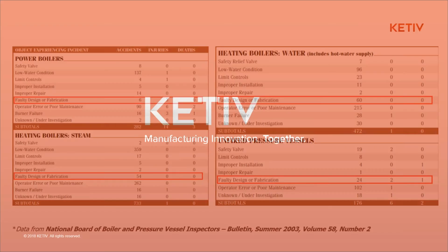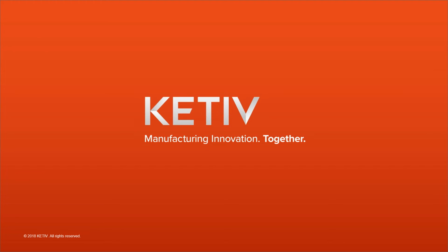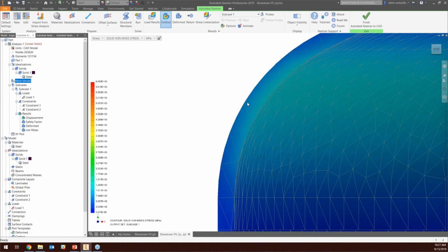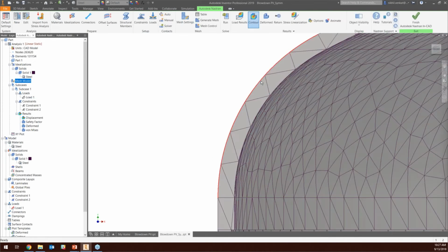Yeah, so there's definitely a couple of questions, and I think some of these can be answered with some of the previous videos that we've done. First off, is there a particular recommendation for number of elements, specifically solid elements, in a through thickness direction? So I'm assuming like on, I think it's through the thickness here. Yeah. You want at least one element.